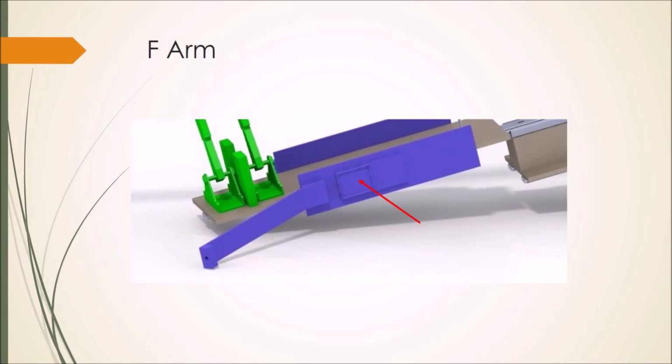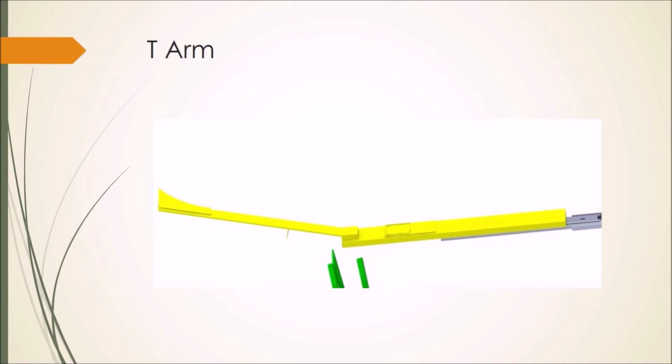Each side of the machine has an F arm system, but only the side where the F is located is loaded. The T arm is located on a secondary sliding system. Initially, the extended arm is folded to rest on top of the main body, which positions a nail protruding out of the arm up towards the top of the machine. A plunger for the small solenoid is hooked into this nail. Once activated, the solenoid pulls the plunger in, releasing the secondary body to slide into the arena.